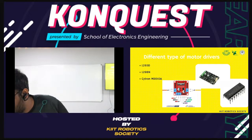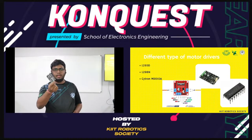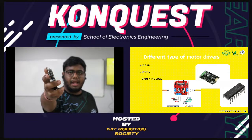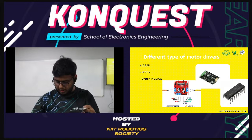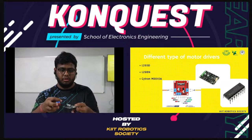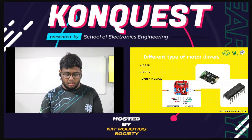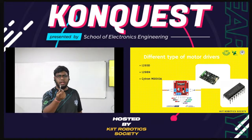The other one which we are using now, this Cytron MDD10A, the 10 ampere motor driver. See, this is a 10 ampere motor driver. Now why? If you see, the pinouts of these two are the same. There are just some four extra expanded pins. Okay, pinouts are approximately the same. Now, why are we going with this only?